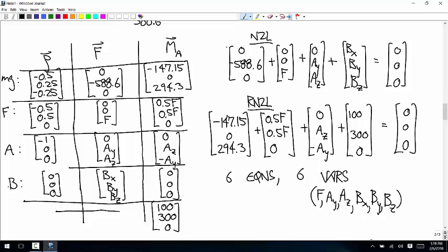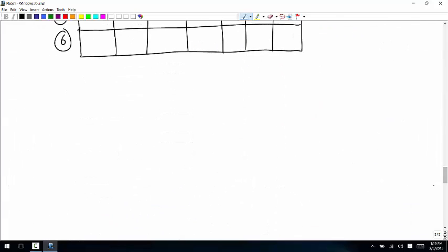So the first equation just says Bx is equal to 0. I'm going to solve this as a system of 6 equations and 6 variables, even though you'd say, well, that's not an equation, that's an answer for one of these variables. Yes, you could reduce down the number of variables you're solving for. That just tells us Bx is equal to 0. But I'm just going to enter this into the matrix as an equation, and it'll come out in the solution.